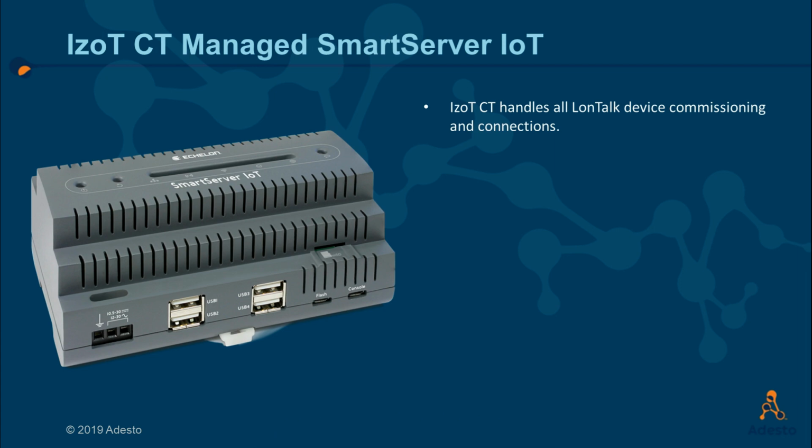Welcome. In this video, we are going to review the workflow to manage the SmartServer IoT using the IzoT commissioning tool. In this workflow, IzoT CT handles all the device commissioning, connections, configurations, adds, and deletes. In a CT managed network, the SmartServer IoT must be configured to operate in independent mode.